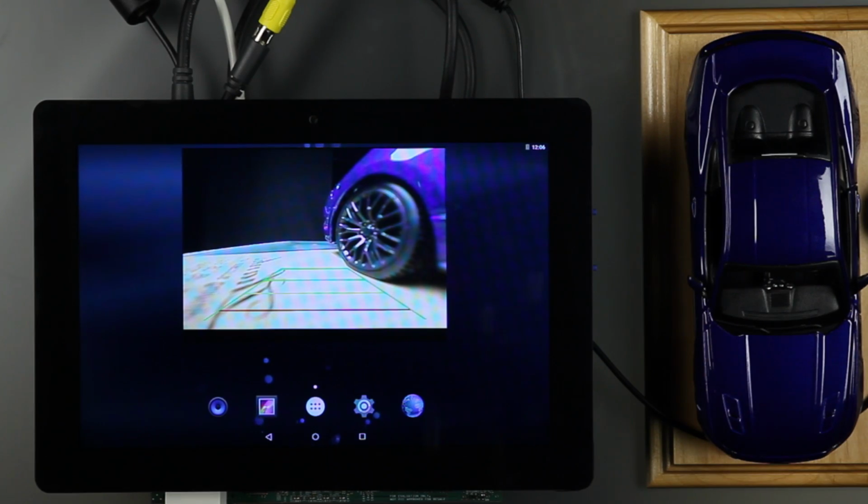Next, I would like to show you the peripheral register monitoring feature of our robust solution for detecting any potential configuration changes in our display controller that could accidentally be caused by some buggy code on another processor core on the device. If I change the alpha blending value of the video pipeline reserved for the rear view camera, you can see that the camera video becomes more faint.